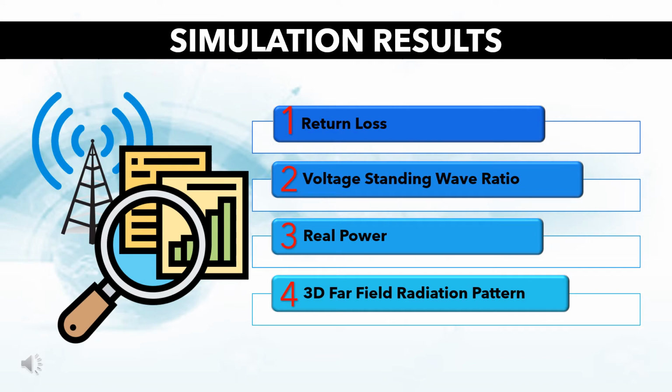Let's turn now to simulation results. The performance of the designed antenna is determined by a few parameters such as return loss, voltage standing wave ratio, real power, and 3D far-field radiation pattern.